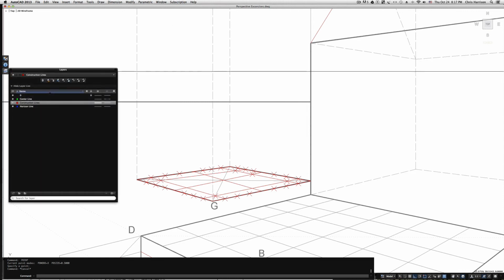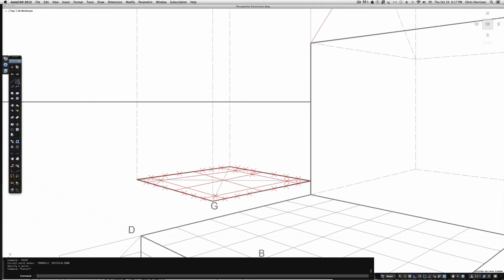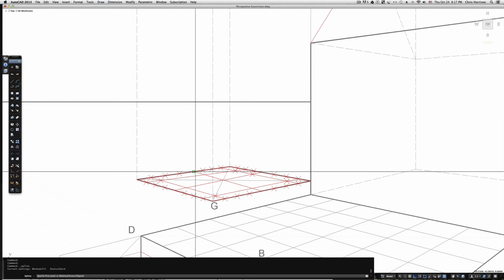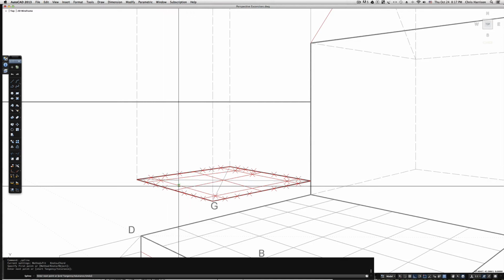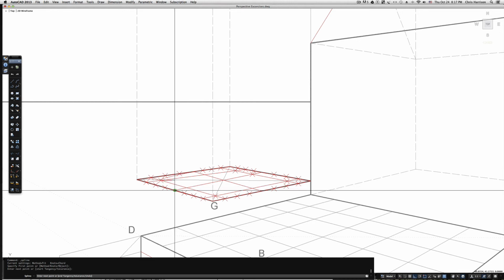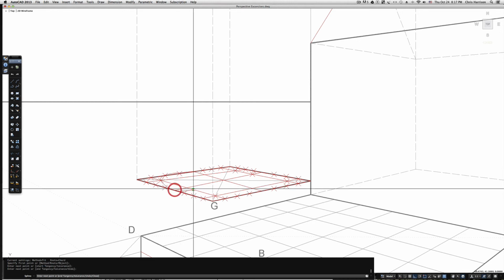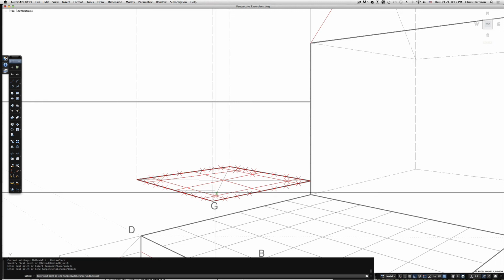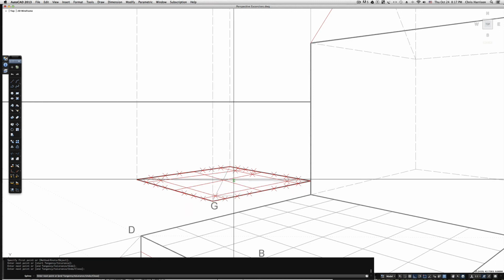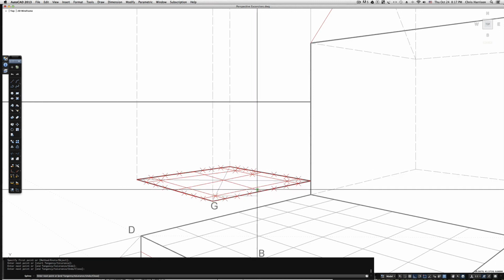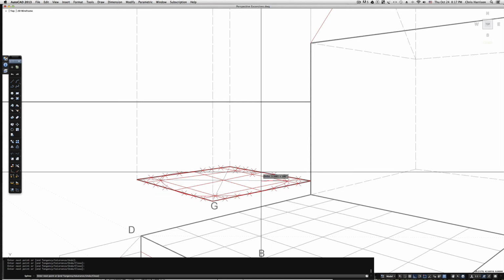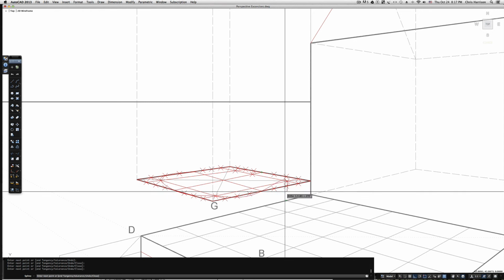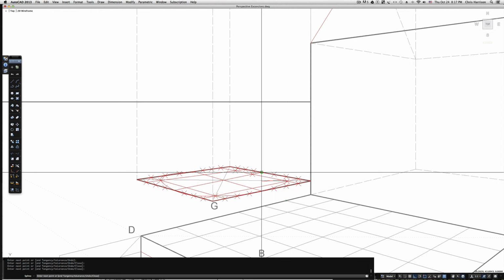The tool that I'm going to use in AutoCAD is going to be the spline. It seems to get me the closest to what I'm trying to achieve. And the reason why I have these points here is that that's the point where the top of the arc strikes before it comes back to the edge. You can kind of see that. And this will spin around here and then touch this here and then again coming back here.